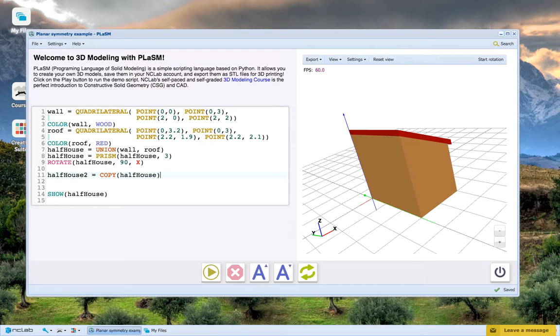Remember that the mirror command takes 3 parameters. The first specifies the object that we want to reflect. The third, and yes, that was the third, determines a main axis that we want our reflective plane, or mirror plane, to pass through. Our second is a point on that main axis that a reflecting plane will pass through perpendicularly.